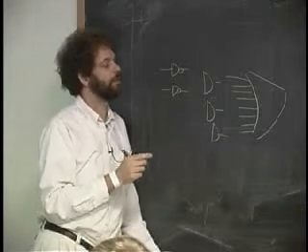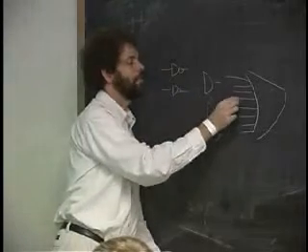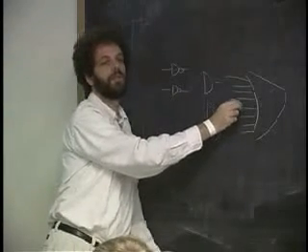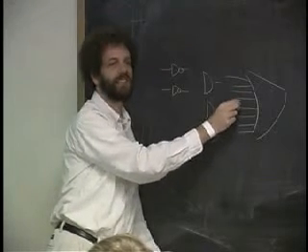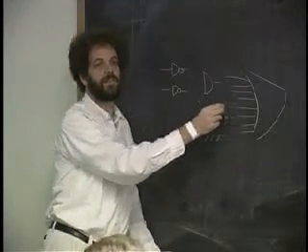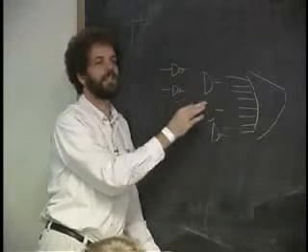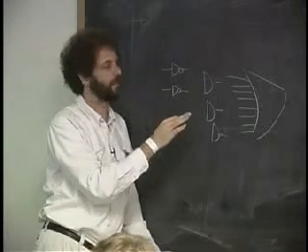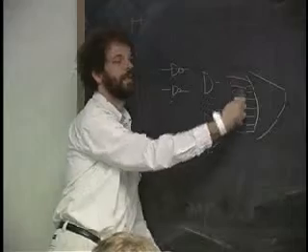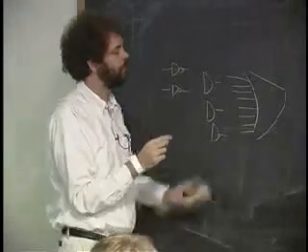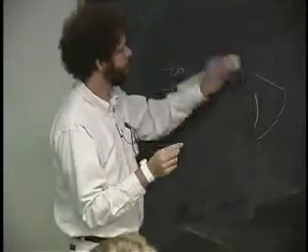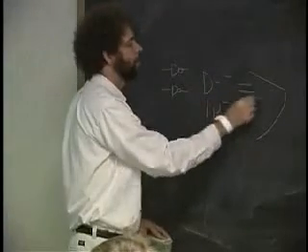The reason it's not true is that if you put 2 to the 30 wires on here, it's no longer 1/billionth of a second. It's now, you know, 100 seconds, or something awful. So infinite fan-in is not a valid abstraction. Fan-in is a measure of how many wires come into a gate. What's more reasonable is to say that there's finite fan-in. So this can get to, at most, let's say 10 wires.